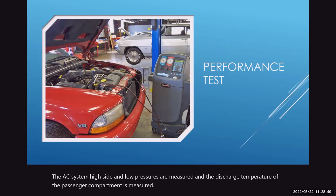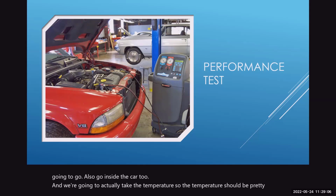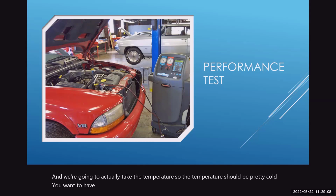So basically, we're looking at the pressures on the high side and the low side, and then we're also going to go inside the car and actually take the temperature. The temperature should be pretty cold. You want to have good performance to make that cool enough for the customer.